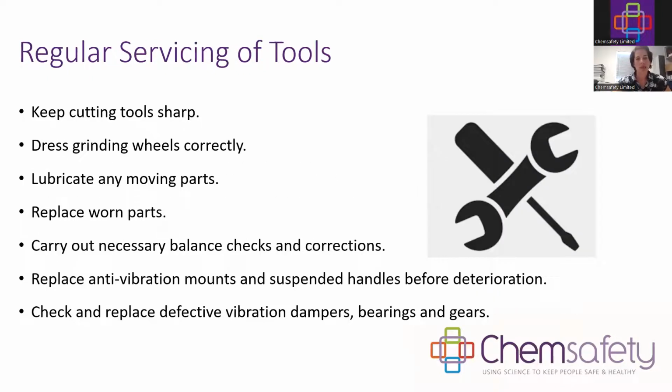Also very important is to make sure your tools are regularly serviced. A tool that is not operating as it should will become a bit wobbly or wonky, and that can lead to unnecessary vibration being emitted. So it's always a good thing to also dress grinding wheels correctly, or lubricate any moving parts, or replace any worn parts. So make sure there's a maintenance program in place where you check your tools and check the consumables to see that everything is operating as it should.